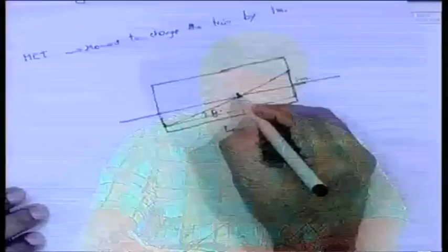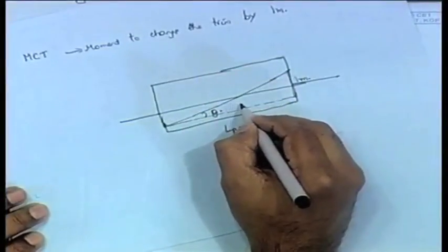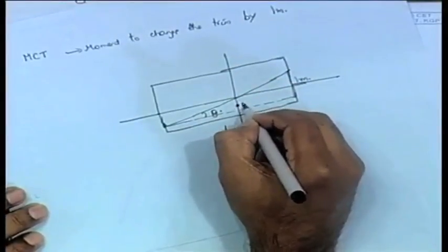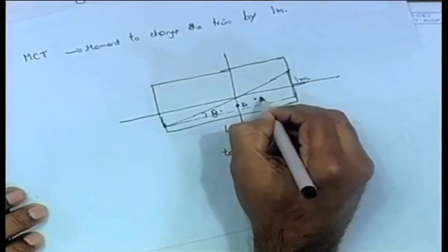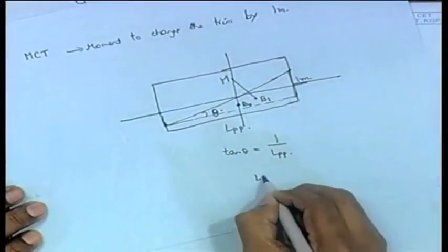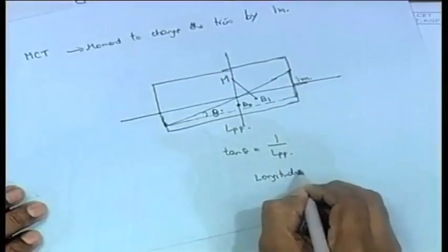So, everything becomes the same. Let us say that initially G is at the center and B is here. Now, B will move to another position, B1. This is another metacenter, we call this the longitudinal metacenter. The other metacenter we were talking about was for heeling; for trimming, we call it the longitudinal metacenter. The mathematics is exactly the same, there is no difference.